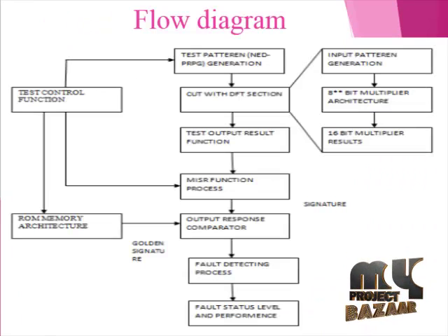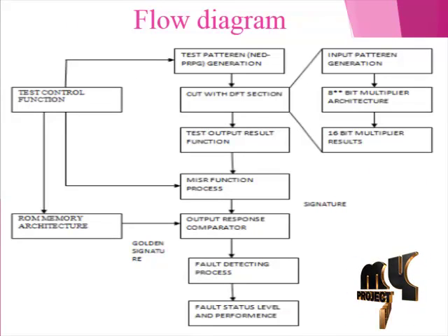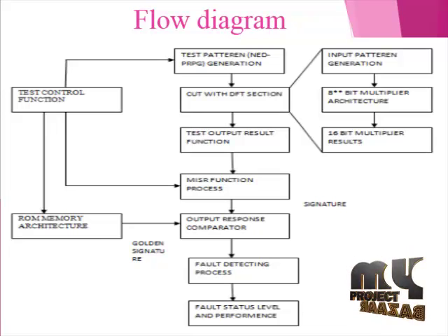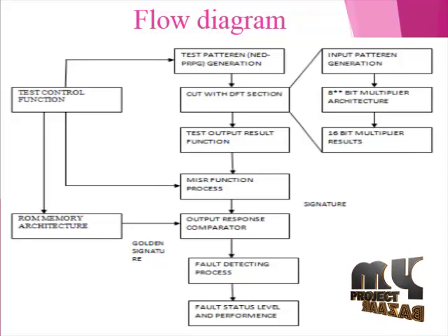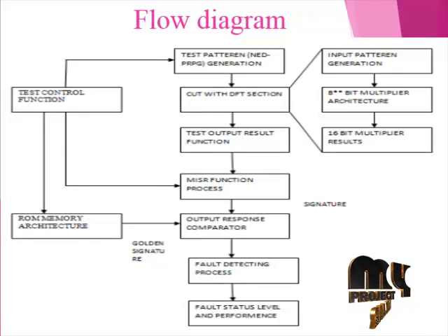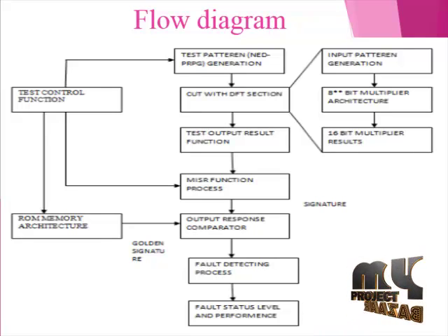Next we are going to see the flow diagram for our project. The advantages of BIST include the capability of performing at-speed testing, very high fault coverage, elimination of test generation effort, and less reliance on expensive external testing equipment. BIST techniques are classified into offline and online. Circuit under test is the portion of the circuit tested in BIST mode. It can be sequential, combinational, or a memory, with its primary inputs and primary outputs delimited.